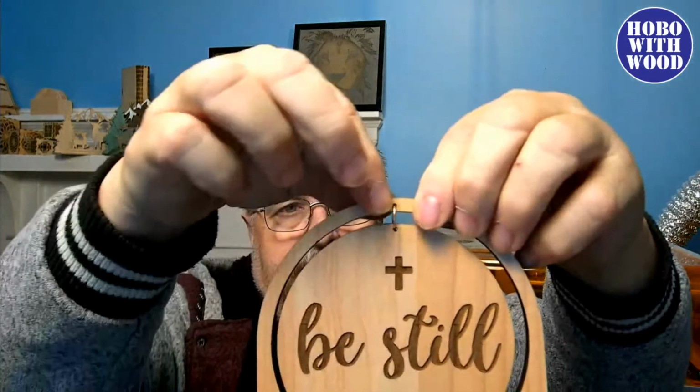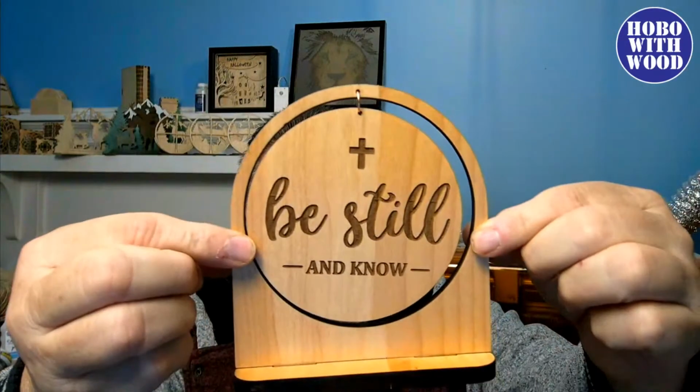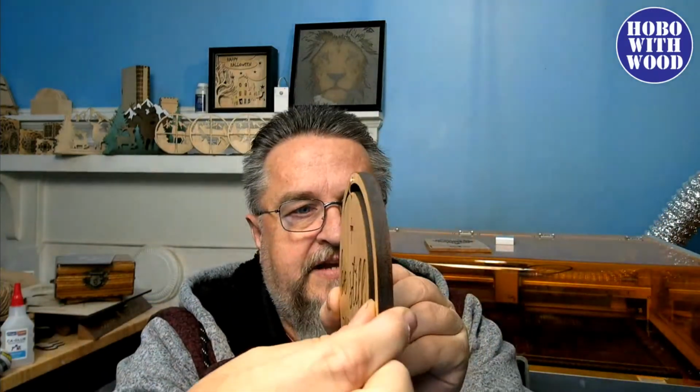I think about the thickness of the material. And this outer ring of this cutout is its most vulnerable point from about there and there up. And since I'm working with 6 millimeter thickness of material, then thinking from a structural standpoint, having the cross section of this be a square, I think it's going to have its most integrity. It's going to be its strongest, because that way there's no one angle that's going to be any weaker than the other, at least the way my mind works.